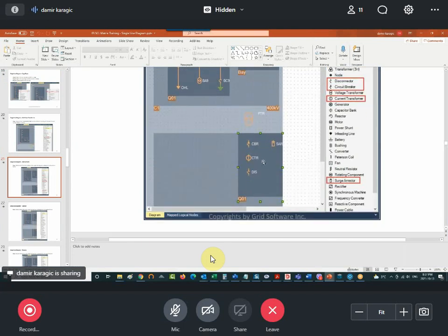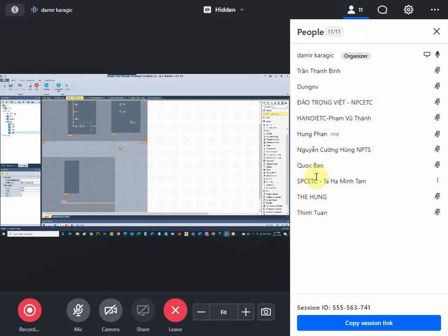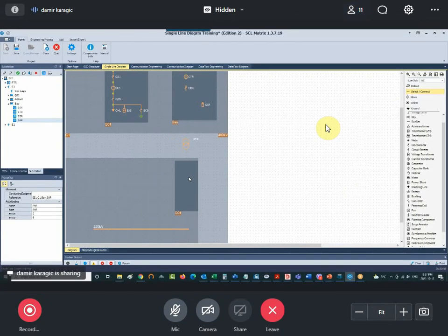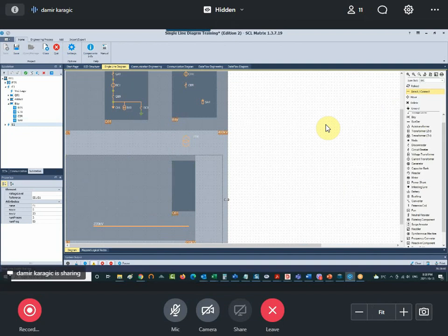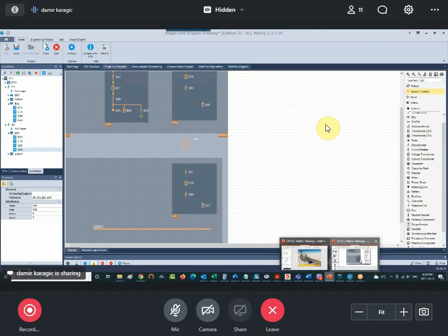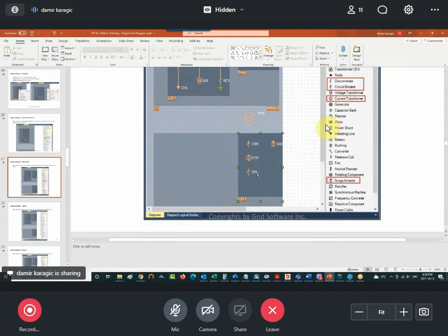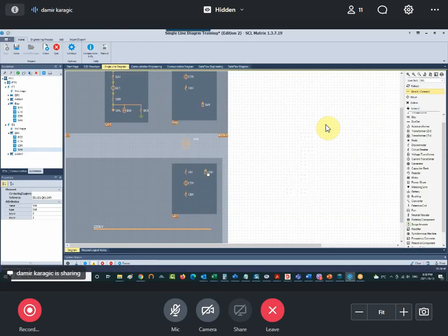And we'll do the same at the bottom. Circuit breaker, current transformer, disconnector, surge arrestor. We'll just shuffle this a little bit here. We'll bring this power transformer here to be in line. Now we'll add this, so adding disconnector. Current transformer, circuit breaker, and surge arrestor. Okay, let me see if I got that right. So disconnector, current transformer, circuit breaker, surge arrestor, power transformer, circuit breaker, surge arrestor, current transformer, disconnector. We'll just move this surge arrestor on this side here.